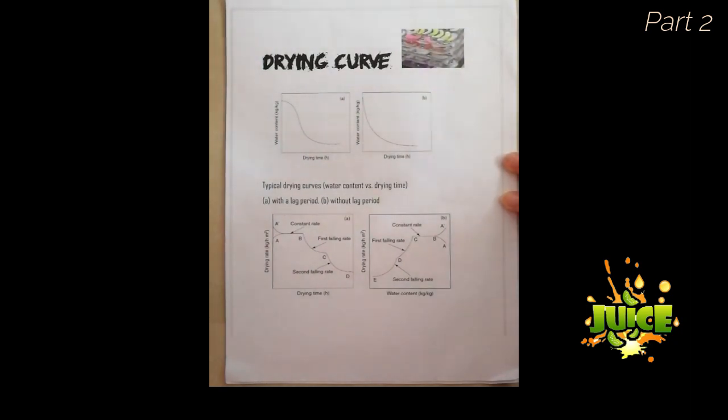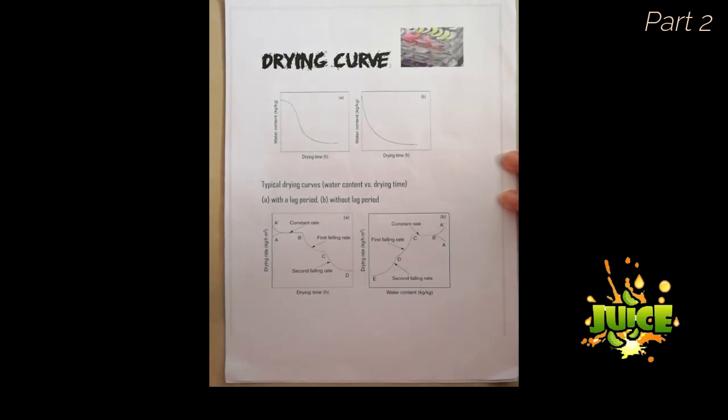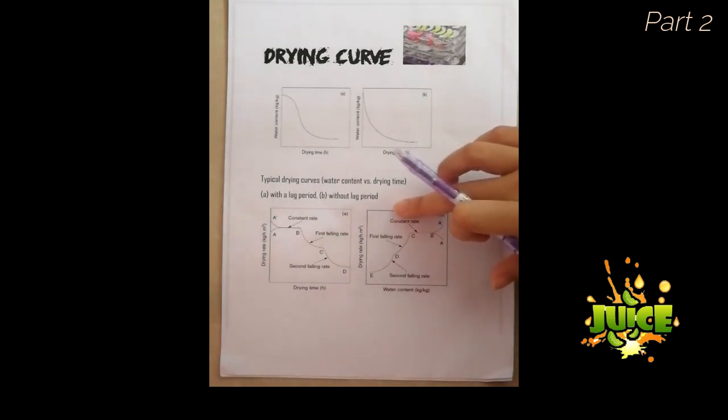In the constant rate period, the water is being evaporated from what is effectively a free water surface. The rate of removal of water can then be related to the rate of heat transfer if there is no change in temperature of the material, and therefore all heat energy transferred to it must result in evaporation of water. The rate of removal of water is also the rate of mass transfer from the solid to the ambient air. These two, mass and heat transfer, must predict the same rate of drying for a given set of circumstances. This is the explanation for the constant rate period.